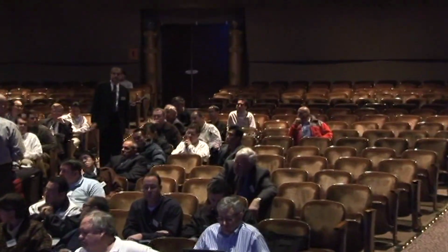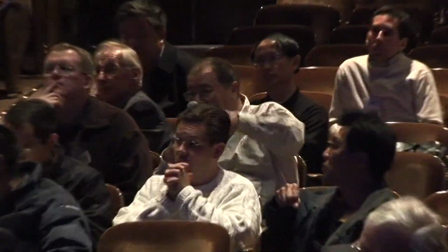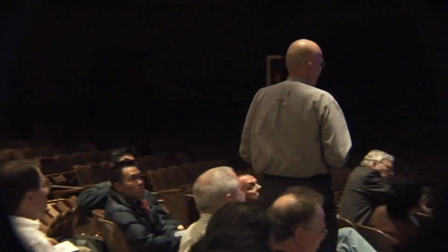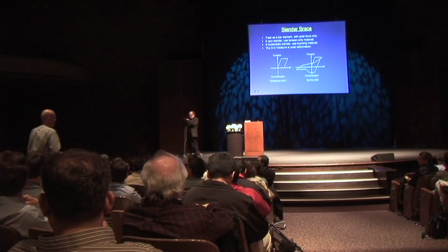We've used Drain-2D in the past to do something like that, and I don't know if the same input variables, like changing the stress-strain curve of the confined concrete, can be imported into Perform. Yeah. So you say you've done it with Drain in the past? Yeah. Anything you've done with Drain, you can do with Perform.